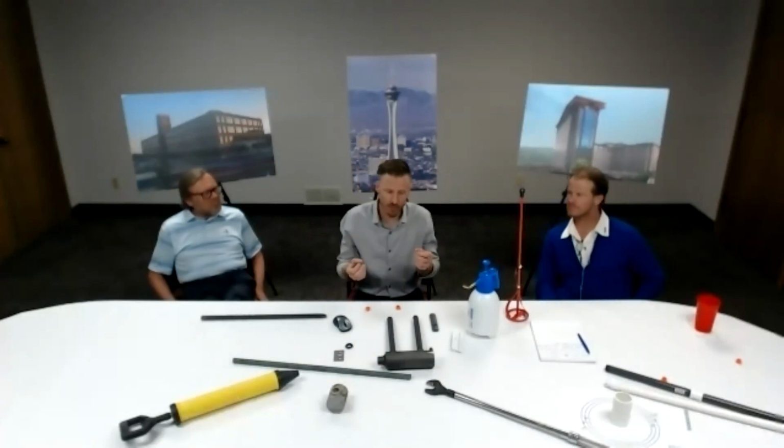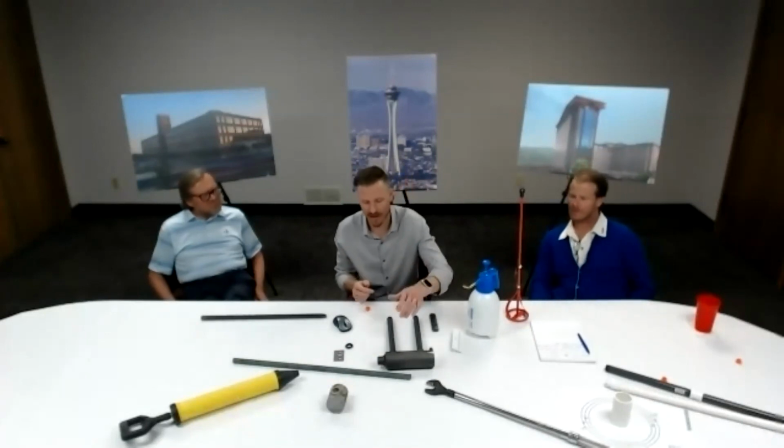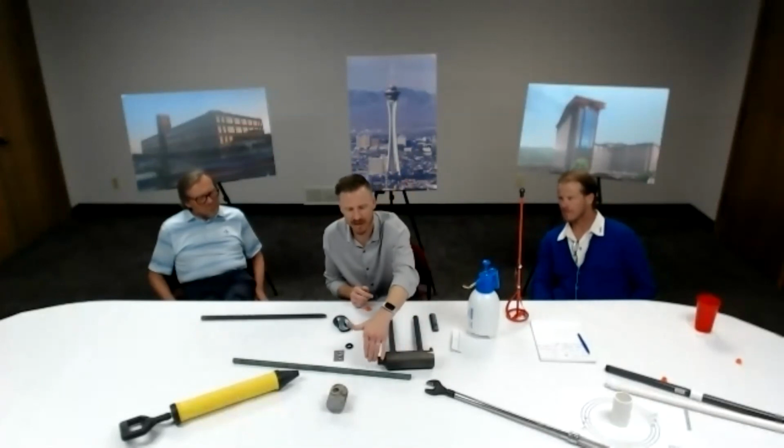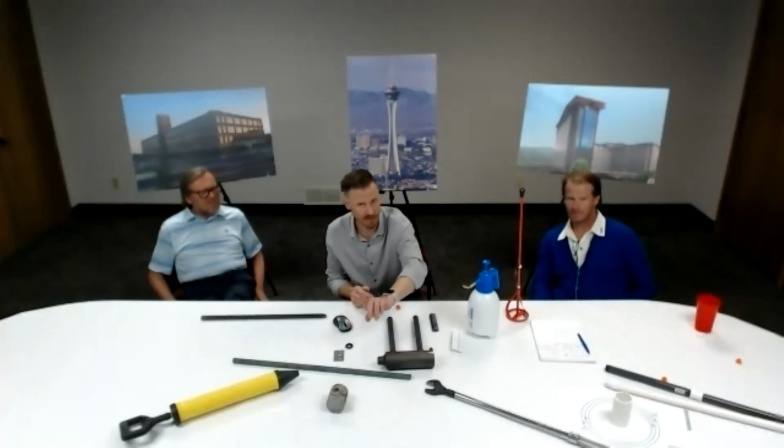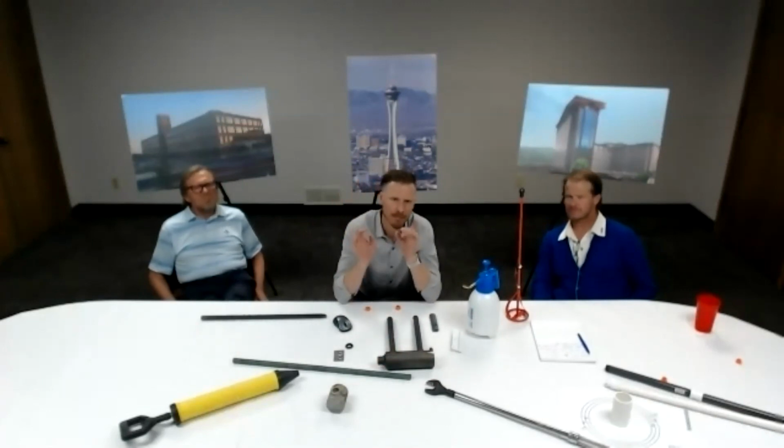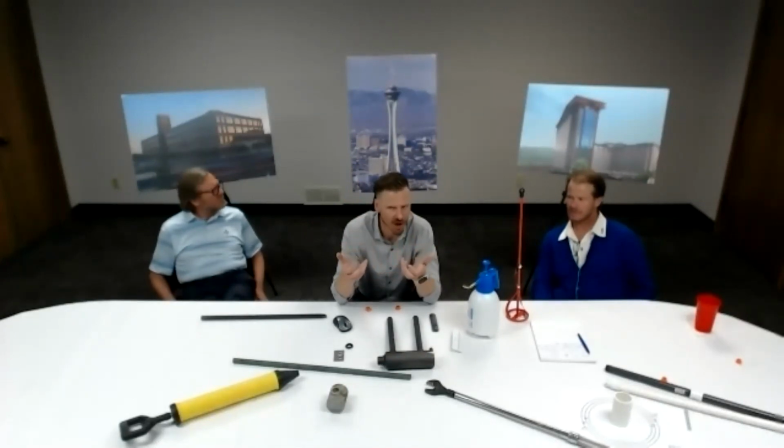But with a 3/4 inch cover on the coupler, and this came up on the projects that we discussed earlier, we're losing very little d. And depending on where the pour strip is located, your moment forces may or may not be that large, or you might not mind losing a little d depending on how tight your design is.